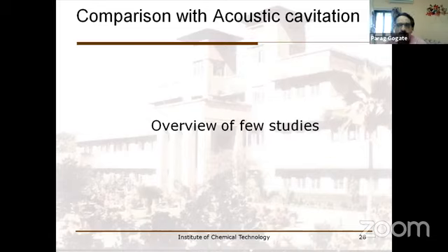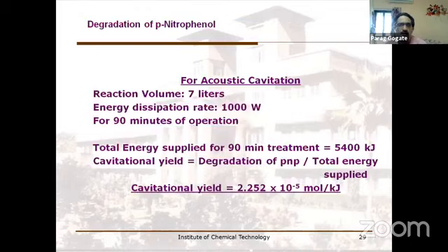Of course, ultrasound does have advantages in terms of higher cavitational intensity. For the presence of solids, ultrasound may be more suitable, because in hydrodynamic cavitation you would have a problem. But let's see some case studies where I'm comparing hydrodynamic cavitation with acoustic cavitation. So again, the initial study was based on nitrophenol. Nitroaromatics, substituted aromatics, have more toxic effects.